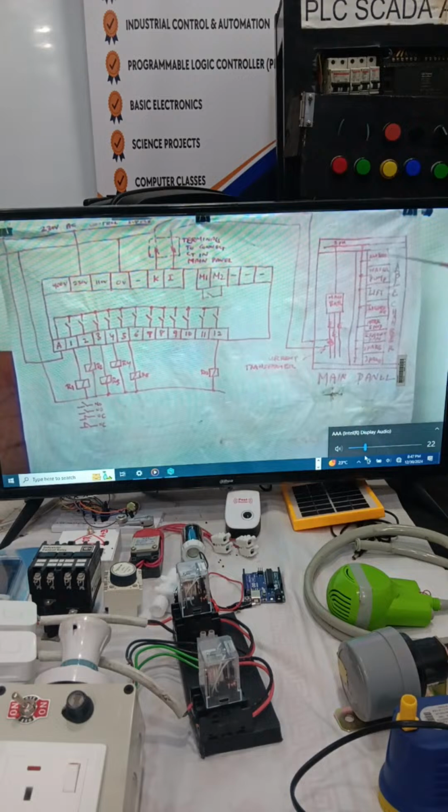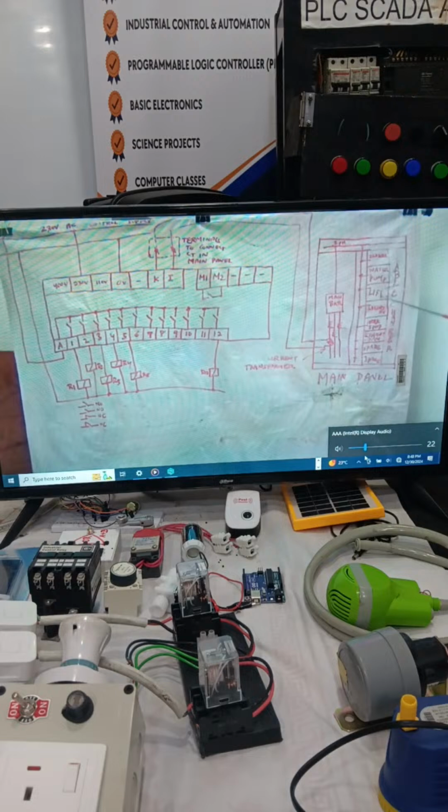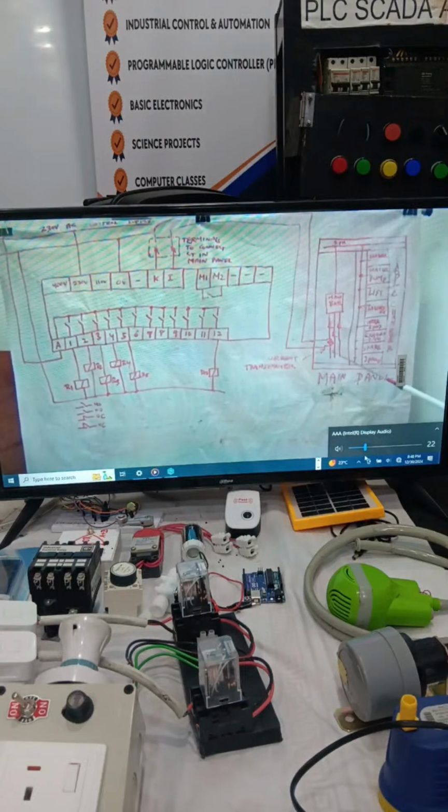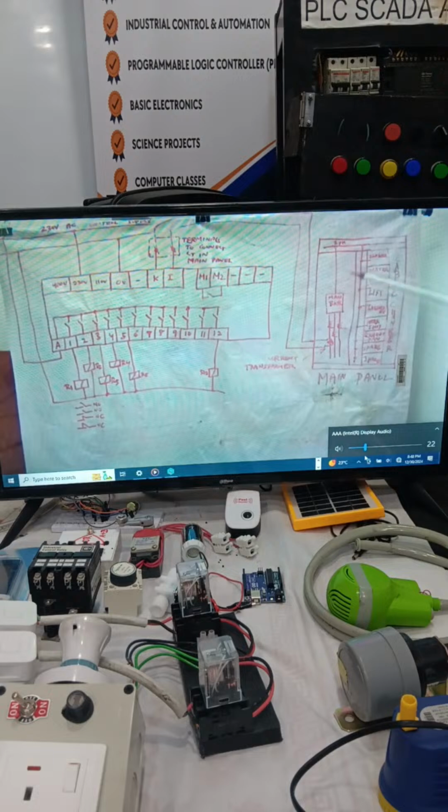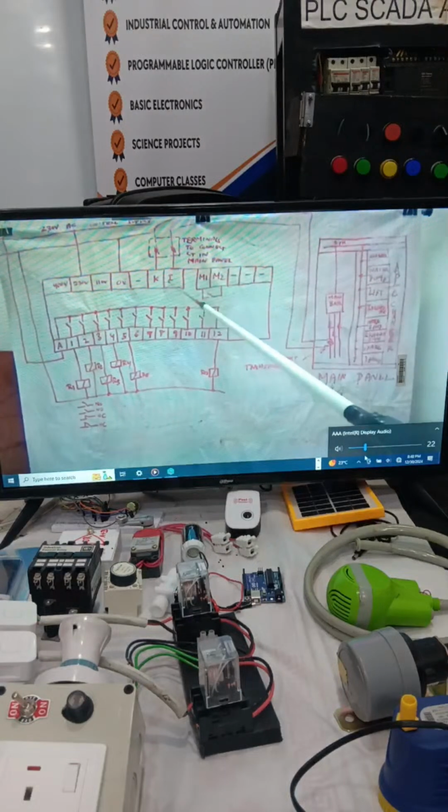So depending upon the operation of these loads, the nature of the current is lagging because of inductive load. These are the current transformers for metering of this panel, but there will be one fourth CT, current transformer. This will feed to these points K and L.